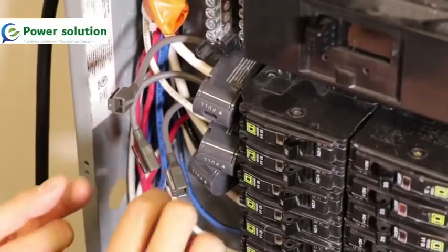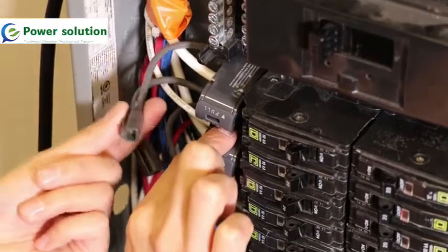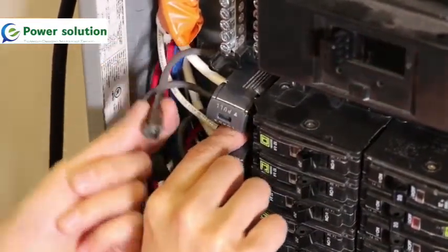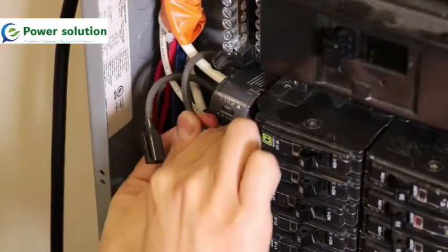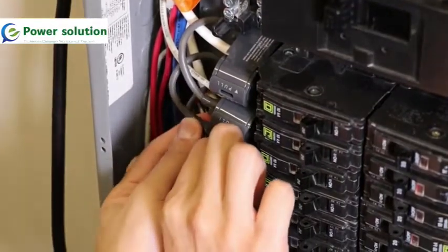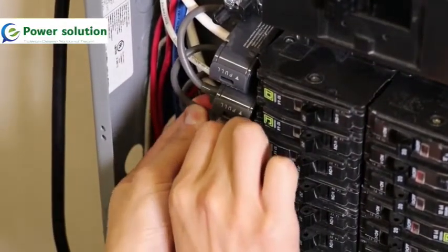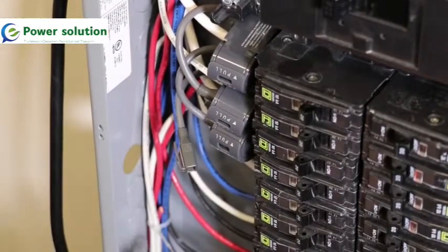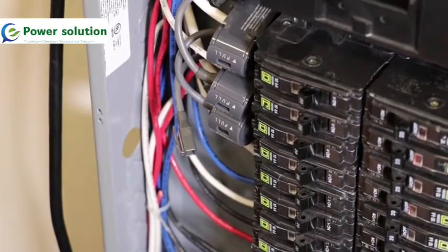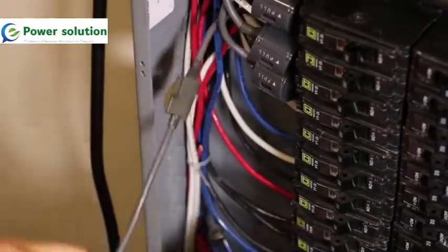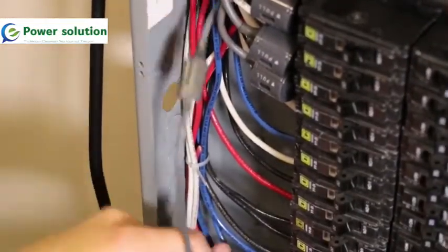After all your current transformers are clamped around the wires, you will take the output of the topmost sensor and feed it into the sensor beneath it. The sensors will daisy chain so that all the information passes through this sensor chain back to the transmitter unit. Now you can see we have a gap between our sensors. Your installation kit will include a variety of extension cables that you can use to bridge these gaps if you don't require sensors in between.